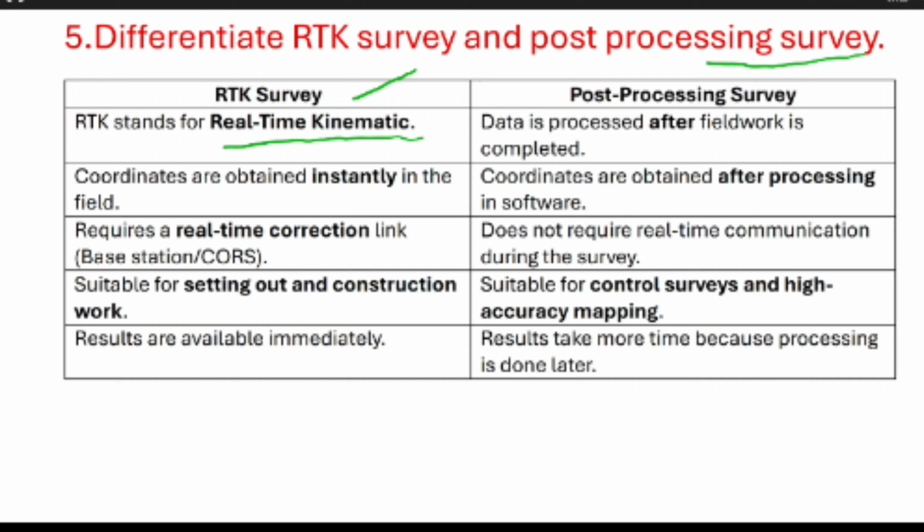Coming to the post processing, whatever data you collect, you have to process after the field work is completed, with the help of the field work data. In RTK, we use coordinates obtained instantly in the field. Here, we get the coordinates after processing in the software.